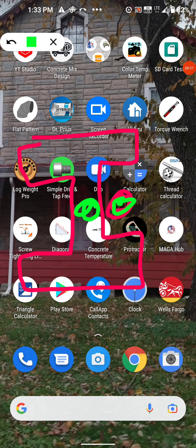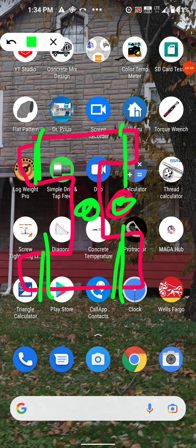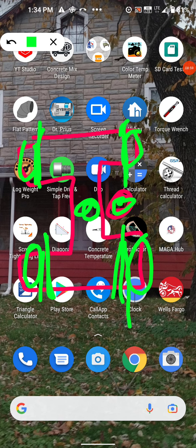Well, if it did that, the issue I have is that you still need something to cause the shear fractures off the tails of these, off the ends. And if you start removing the load, you start removing the ability to cause this to fracture all the way here, all the way everywhere. It did not. So it fractured while it was still on top of the columns. That's why you're missing the tails on all these. So the load, when this went to failure, all of this sheared. These sheared at that level. Remember, it looks like a ground up failure.